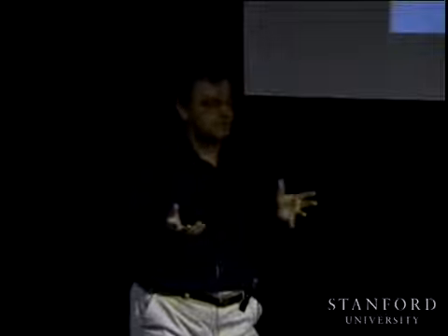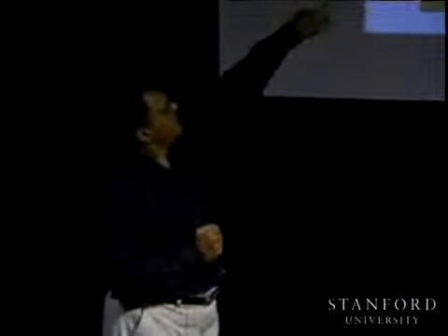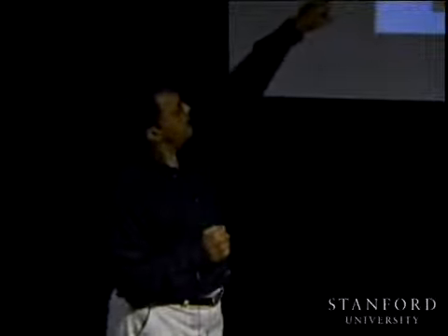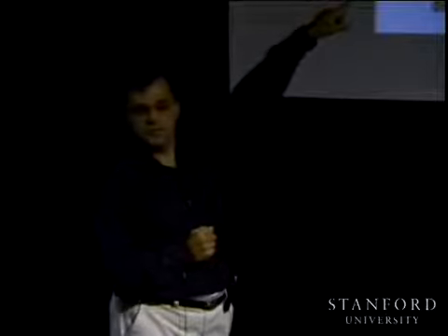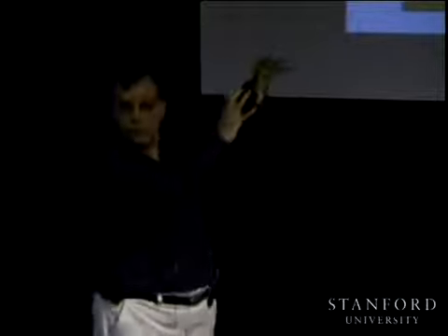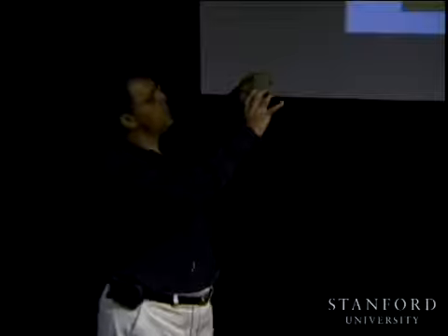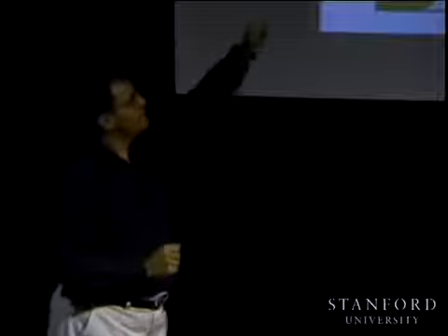Basically, we take the obstacles and we grow them by the size of the point robot, if you want. In which case, if you look at the red dot there, if we plan a path for the red dot that doesn't collide with these grown obstacles, then we know for sure that the circle is not going to collide with the smaller target obstacles. And so then we just have to plan a path for one point in that space, which can be done in many different ways geometrically.